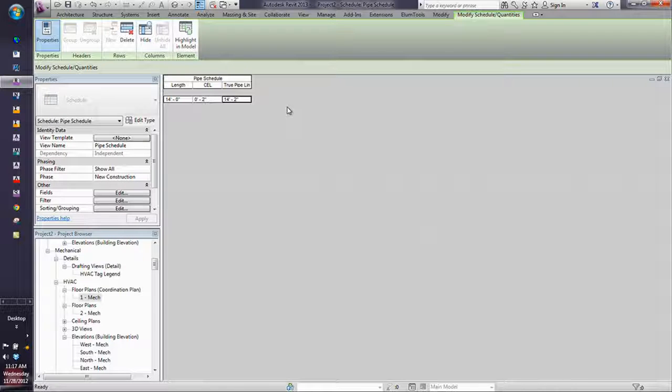If you do it by instance, that means you can do it by each individual pipe. But you could also do it by type if you wanted to. I could go in and have my ductile iron pipe type and say, I want to include 2 inches for this because it's a mechanical joint pipe, whatever I want that depth to be. I just like to do it by instance so I can adjust it on every single piece. That way I can get a really true estimate in that value. Pretty cool? Real simple thing to do in there.